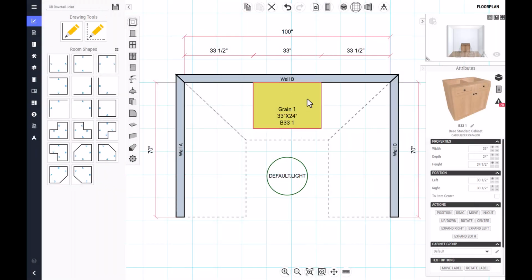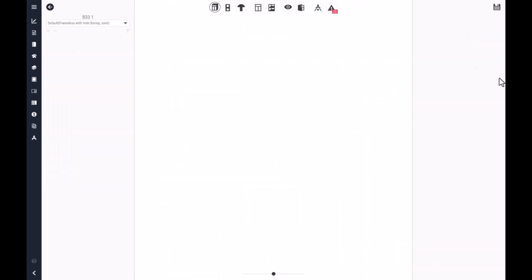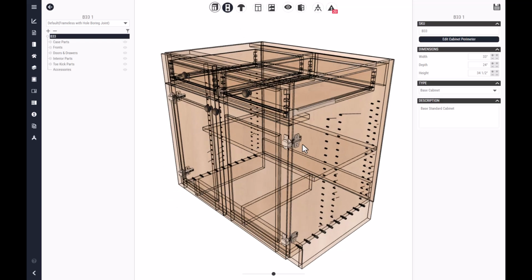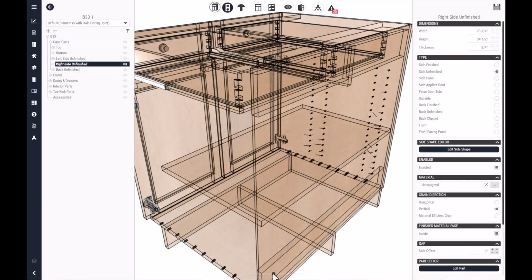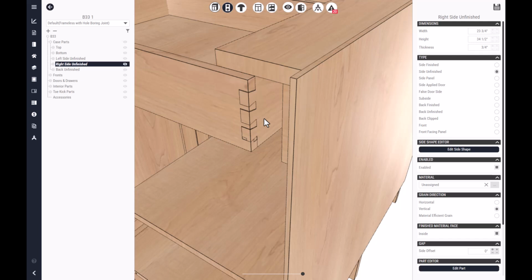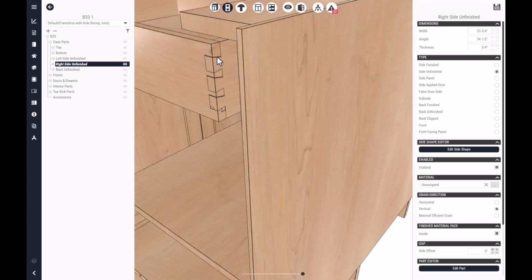Create a test cabinet with a drawer box and open the wireframe editor. Turn on Show Processing so the generated processing can be inspected. Verify the tail width, tail slope, maximum tail spacing, minimum pins width, first tail margin, last tail margin, and all three adjustment settings. Also verify the selected inside corner corrections and confirm that the matching profiles align correctly between the connected parts. If CNC connection parts is enabled, verify the parts are cut to the correct pre-joint lengths.